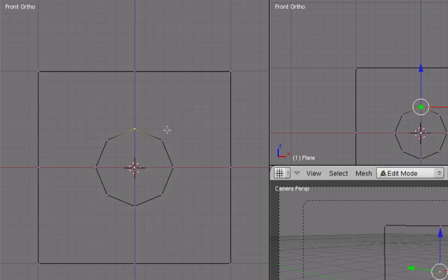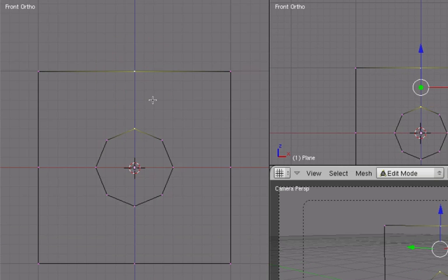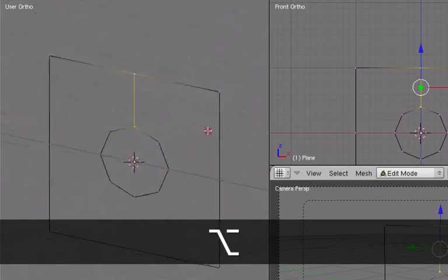Well, Blender allows you to erase vertices, edges, and faces, but also has very convenient tools to do the opposite, to create new edges. Well, how you do that? Before I can create the face of the polygon, I have to create my edges. So right now I have 2 separate pieces of geometry. I can right-click on this vertex and then shift or right-click on this. Now we have these 2 vertices selected. If I press F, Blender will join them, creating an edge. See? Isn't that beautiful?